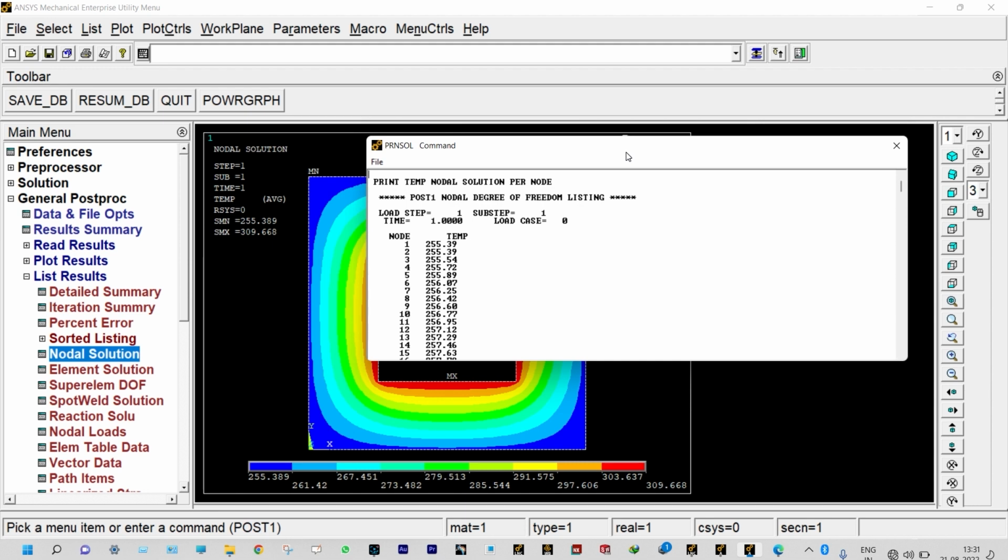These are the different ways of modeling, and in this case we don't know whether this is perfect or not, because if we go on remeshing again and again, the results will vary, right? And when convergence criteria are achieved, we can say that our result is optimized, right?